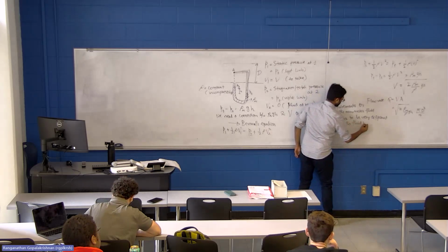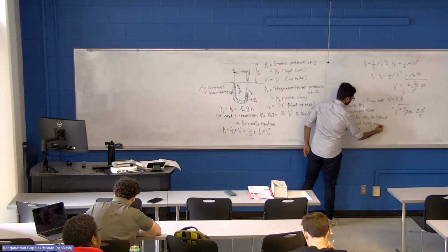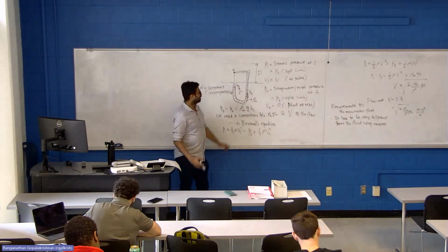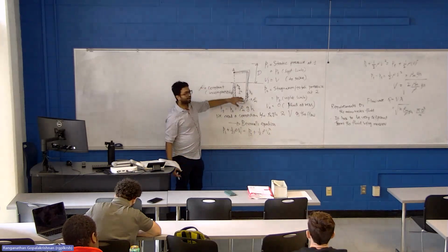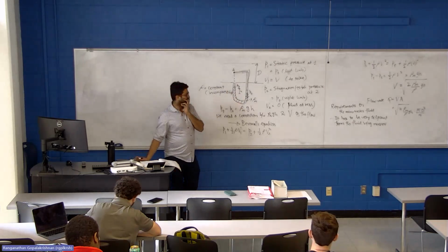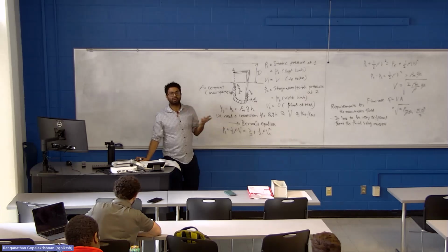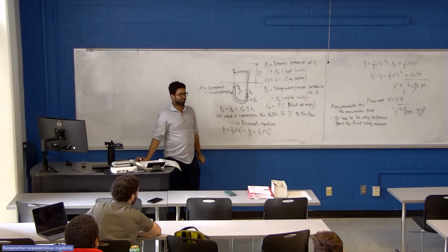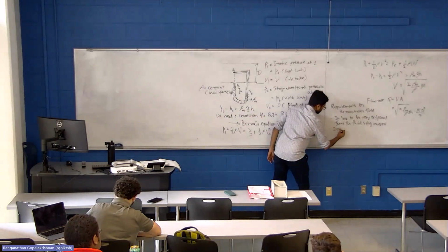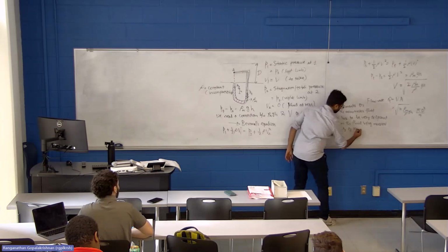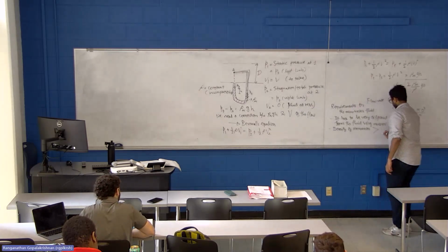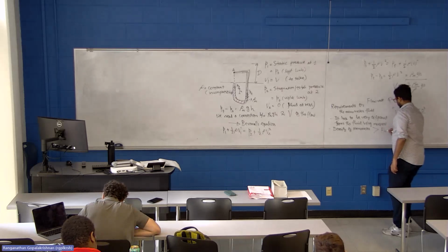And the fluid being measured, if it's air, it can't be air. In fact, air is a very terrible manometer fluid for a reason I'll tell now. If your flow is water, you can't have water because it will just mix. Okay. So then what is the requirement? It can't be the same. It has to be different. In what aspects must it be different? Density. Density has to be distinct. The density of manometer fluid must be greater than the fluid being measured.